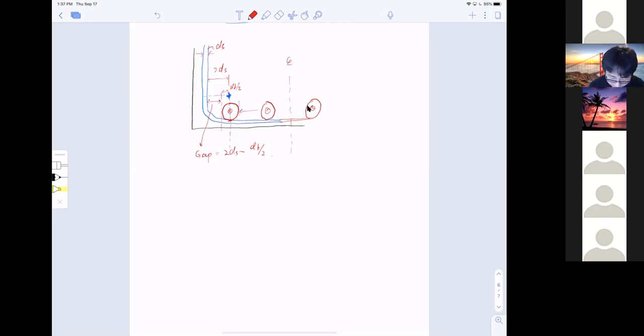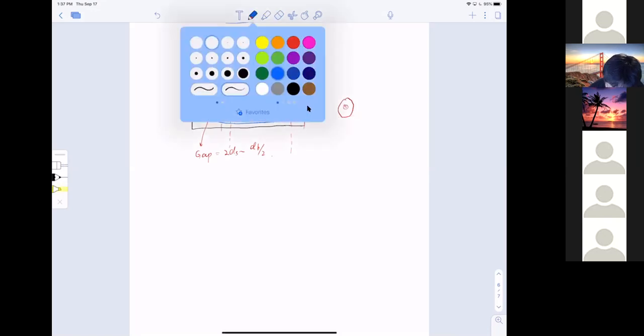So this spacing right here, you know how to determine that, right? Yeah, that's the same as the vertical, but with 3 criteria: the bar diameter, 1 inch, or the 4/3 aggregate size. I'm just going to call the spacing T, okay? Now, the spacing between these 2 bars is the same. Mm-hmm. So assuming I'm going to have 4 bars, I believe that's the problem, right? Yeah, 4 bars.